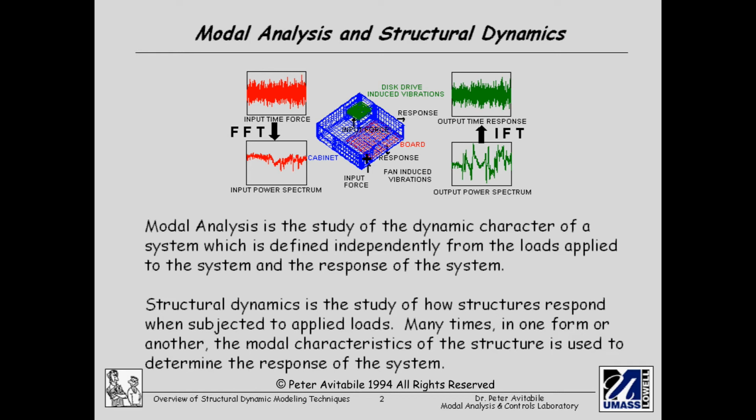So in the same way we may have a cantilever beam and you put a force at the tip of the beam, you know that there are characteristics that tell you how that beam will deform. And it doesn't matter what the force or moment are that you apply on that beam. You know that the beam is defined by things like bending moment of inertia, Young's modulus, density. These are characteristics of the system that are independent of load.